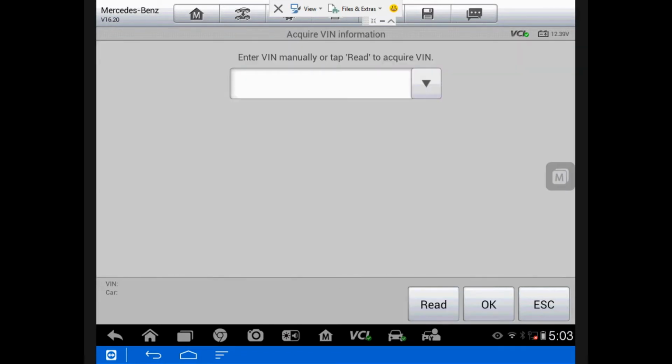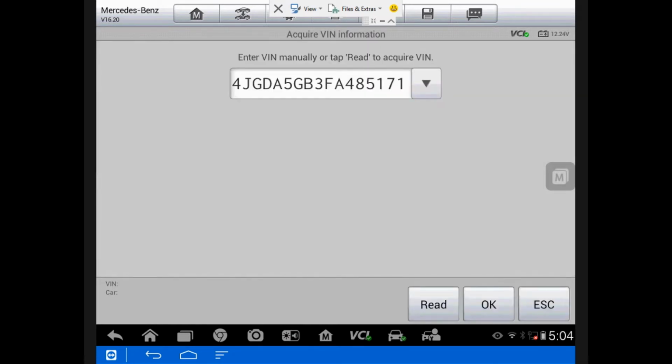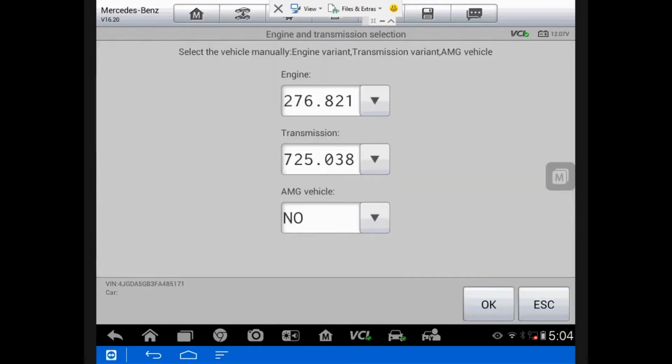So we've got the scan tool hooked up. We're going to go in and configure it so that we can look at some scan data. Basically what we want to look at here is intake manifold data or boost data. I'm not sure how they'll classify it on this car. Mercedes does it different ways with different cars. So we're going to let the scan tool ID the car.